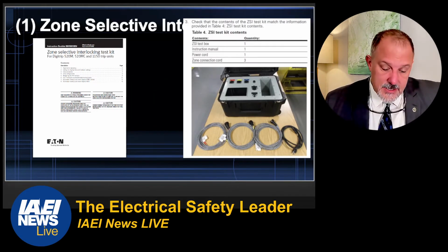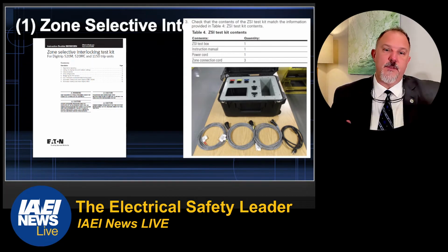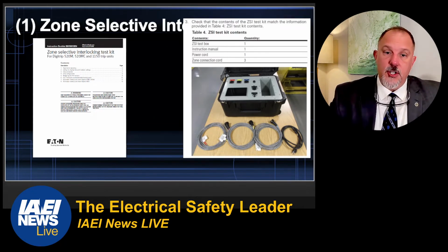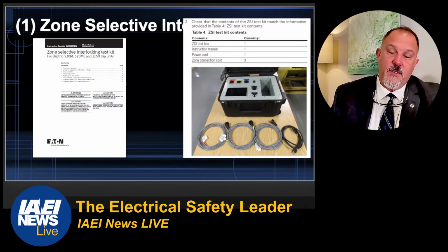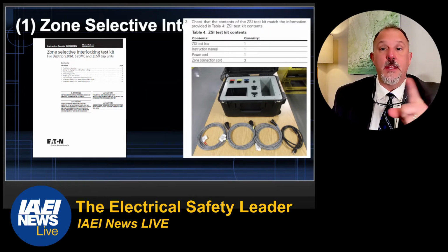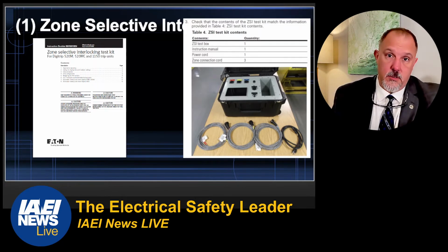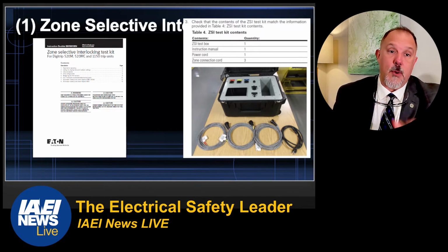So this is a test set that you can either acquire or get from the manufacturer of the overcurrent protective devices that you're seeing on the job site. I would say that one manufacturer's test set may or may not work for the other manufacturer's equipment. So always consult the manufacturer to understand what you need to do to properly test that technology.